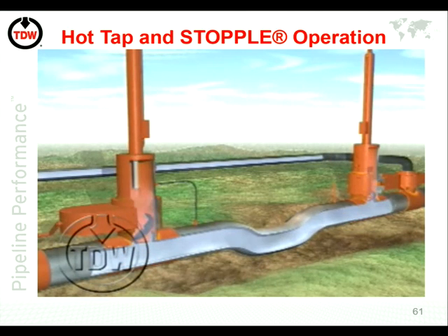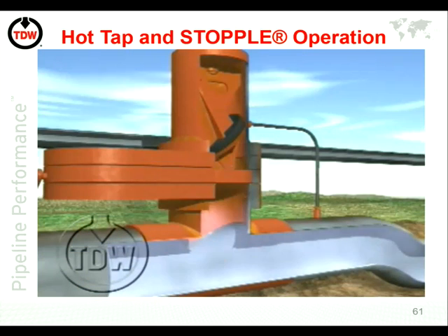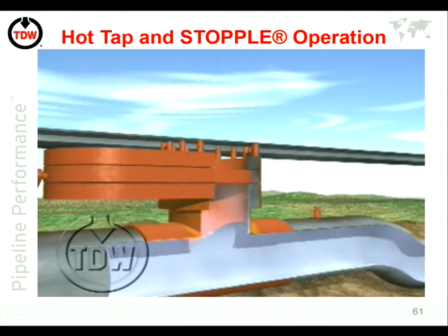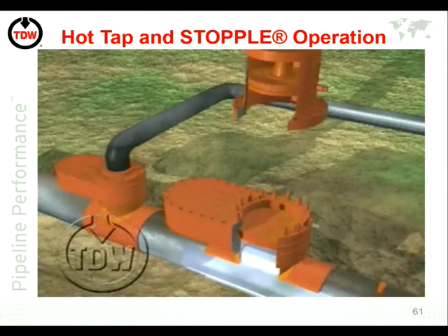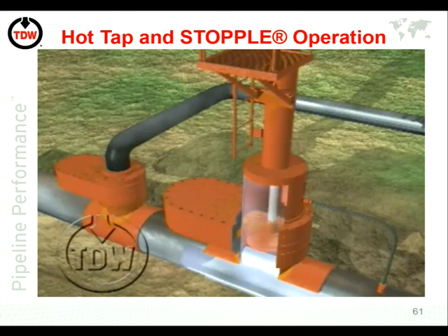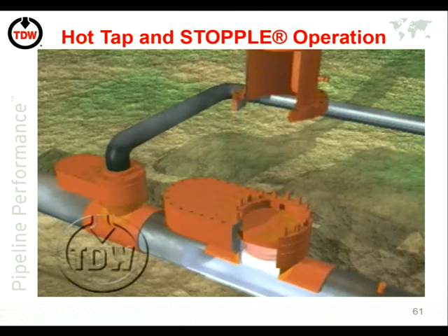And again, we'd isolate our section with the sandwich valves. And this is where the plugging, the small plug that goes in, and so the locker ring there locks it in place, so no pressure can come past that fitting now. And what that allows you to do is remove the sandwich valve and all of the fittings associated with it.